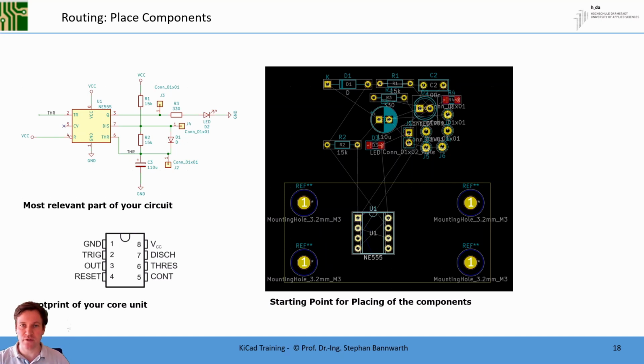Two things which we haven't considered yet are the test points. The test points will be placed as well as possible once we have laid out our main circuit. And the other thing we haven't considered yet are the LED D3 and resistor R4 for the power LED if the power is connected. This routing is also done after we have routed our main circuits, since a connection from VCC to ground is not that difficult to realize, especially if we use SMD technology as in our case.